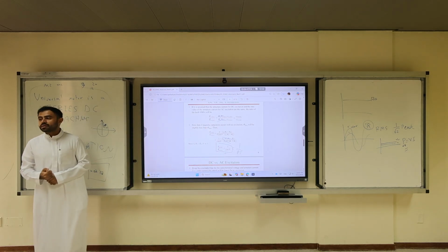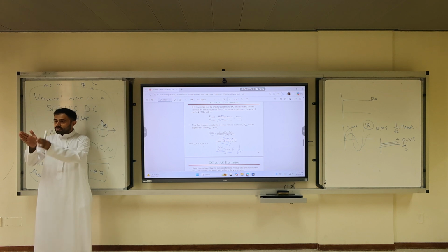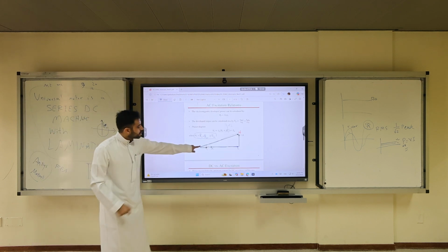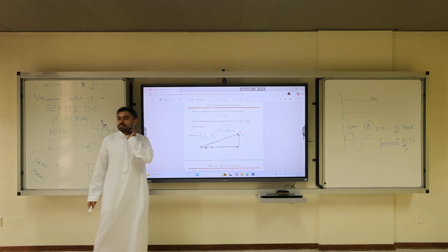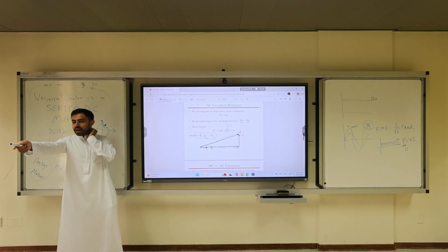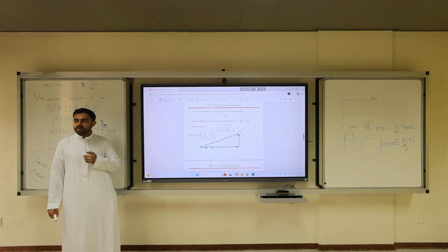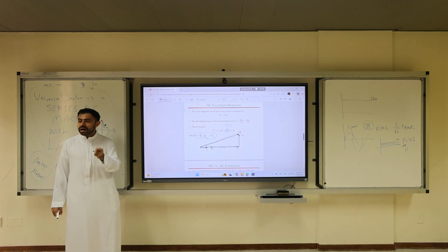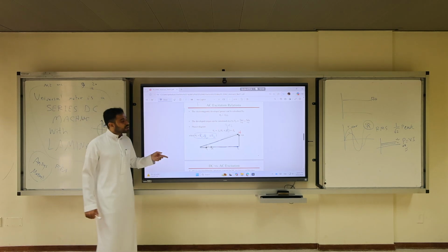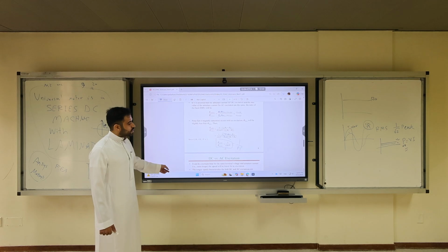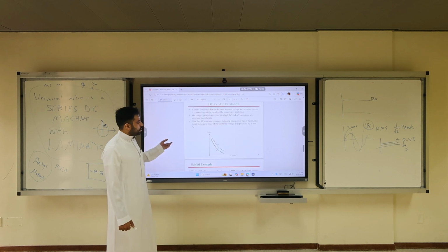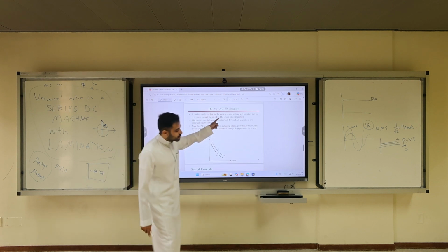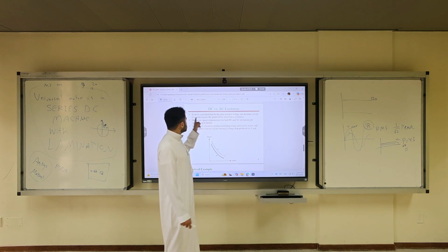What is the power factor? It's the cosine of the difference between the angles of VT and IA, the angle between VT and IA. And how do you control this angle? From the supply, and there is the load. So we notice here that the universal motor, if you apply it on AC, the speed is controlled by power factor. That's one key feature about speed control of the universal motor. Are we going to do it? Probably a little bit.